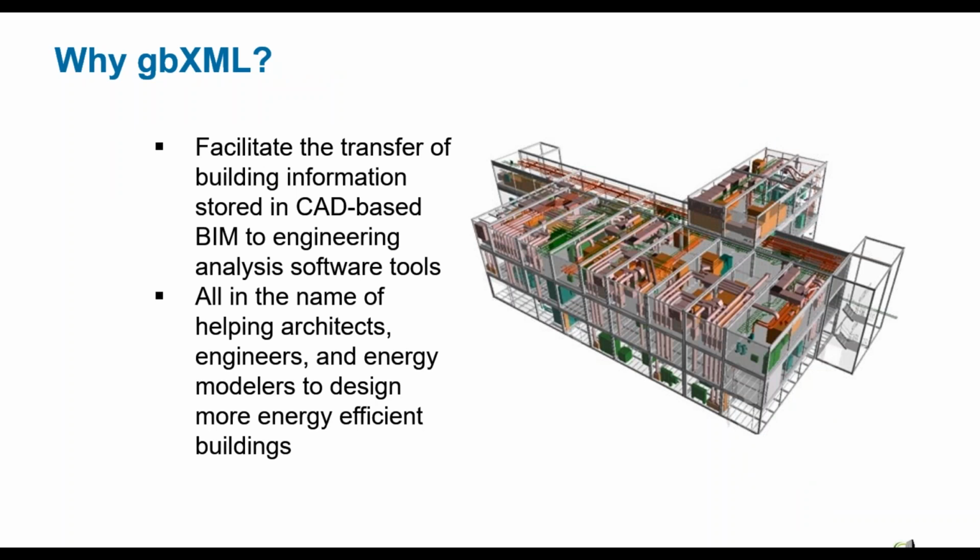So why gbXML? I mean, what are the benefits of it? Well, think of the BIM as a database of all building information. And somehow we need to get that information out of the BIM and into the tools that allow energy modelers to create accurate building energy models, perform load calcs, lighting analysis, computational fluid dynamics, and much more. So gbXML actually helps facilitate this interoperability of transferring the information from the BIM to other software tools.